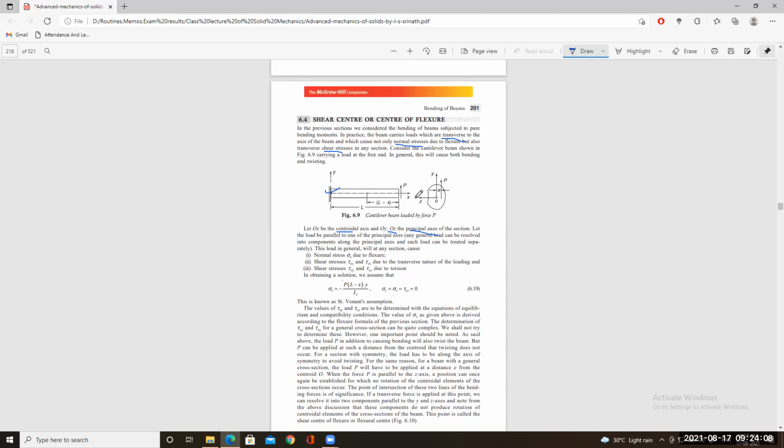We are ignoring the intermediate stresses, and as per the definition of major and minor principal stress, there should not be any shear force acting within this plane itself. That is the benefit of principal stress. That's why we always use these positions as principal axes in our consideration.